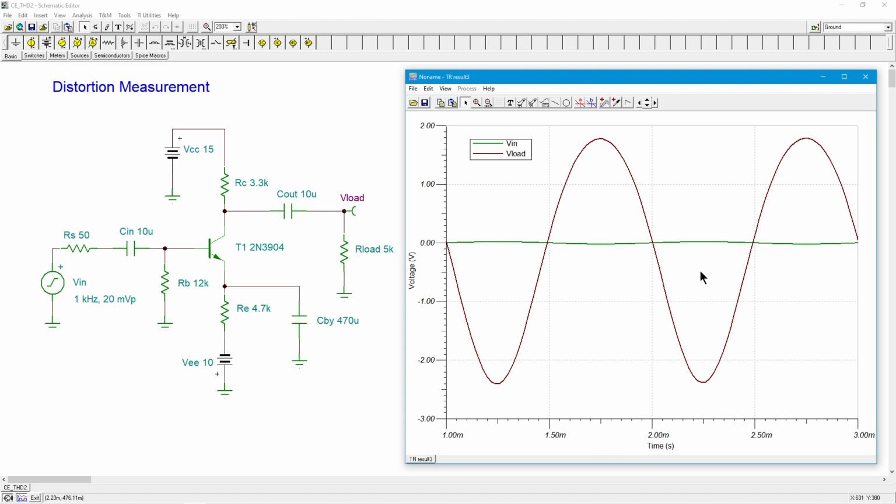The first thing I'm going to say, by the way, is if you can look at the waveform and see an obvious asymmetry in the wave, whether to the positive or negative, or even side to side, what we call quarter wave symmetry, right? If I split this down here, is this half like this half? That's quarter wave symmetry. If you can see that there's a difference, you pretty much have over 1% total THD. If you can't see it with the naked eye, that doesn't mean you don't have distortion. It's just not easy for your eye to discern, let's say, 0.2% THD in a sine wave. But we have machines that can do it for us, right?